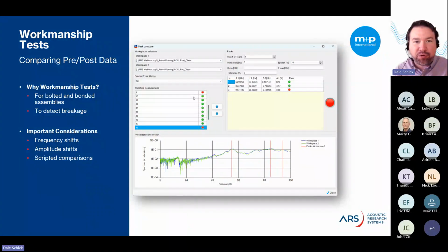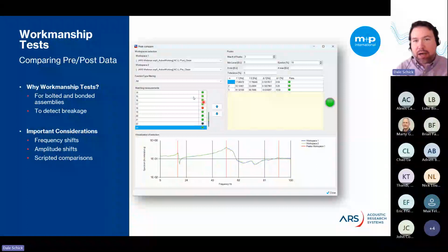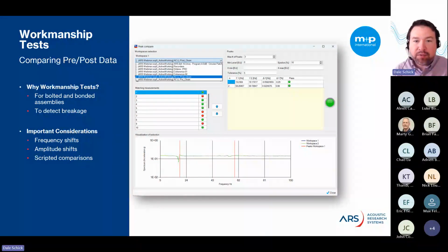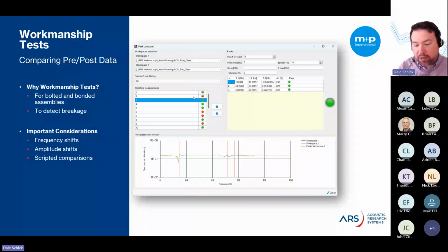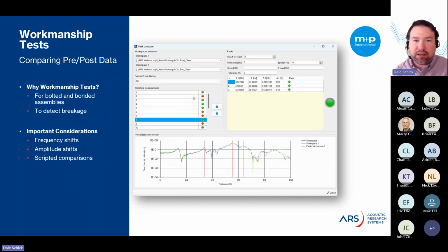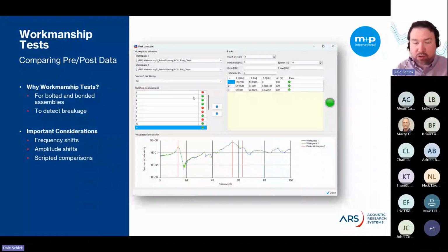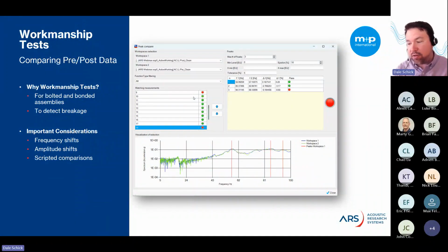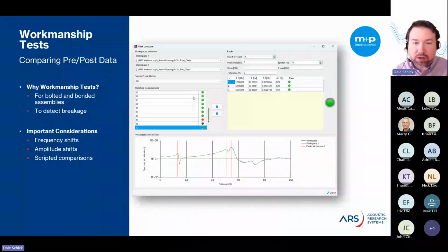So as we scroll through these processed results, you'll get a nice green light for however many peaks you decide to choose and at what peak epsilon or the quality factor of that peak. And then it'll give you a red light if that doesn't meet the pass-fail criteria. So in this way, you can quickly thumb through hundreds and hundreds of channels of data and do some post-test analysis to determine whether or not to continue to the next level if you're doing a vibration test, or whether or not the test is valid when you're doing an acoustic test.